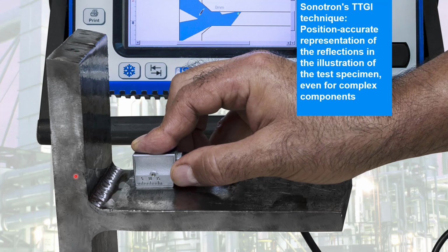You have a test piece here. As you can see, this test piece is a T-joint, and there is a probe over here at a certain distance to the weld. This probe looks like a MWB probe, but in fact it is a phased array probe. We have 16 elements inside here. You see the thick cable here also. There are 16 elements which are controlled by the electronics, and they test the weld somehow.